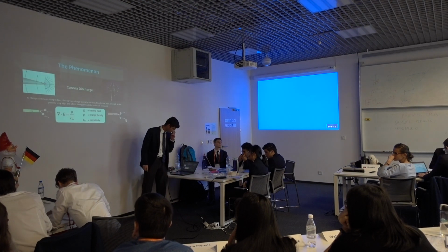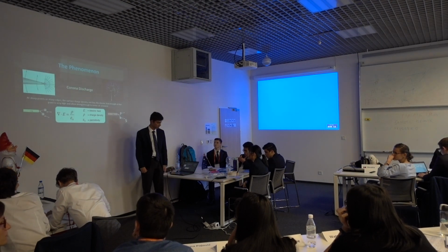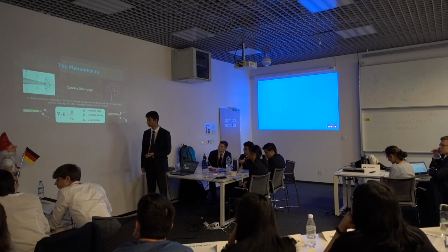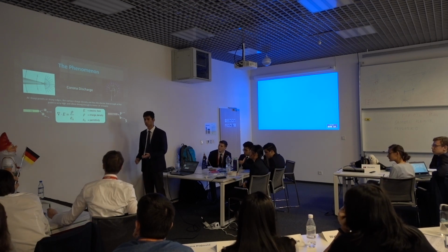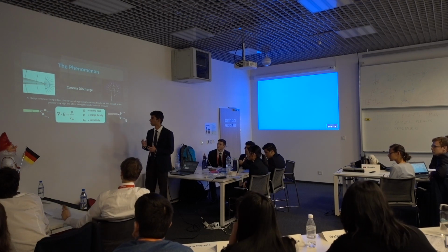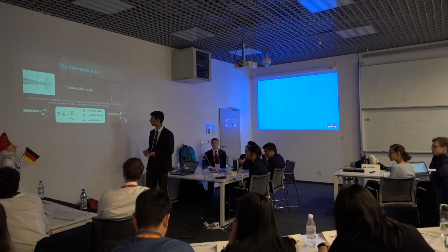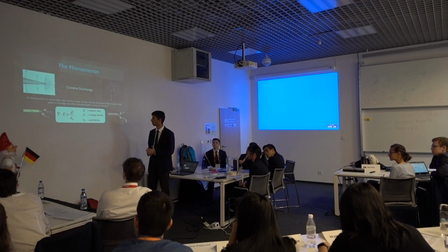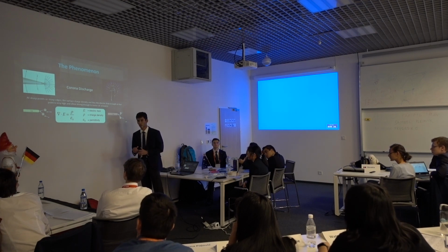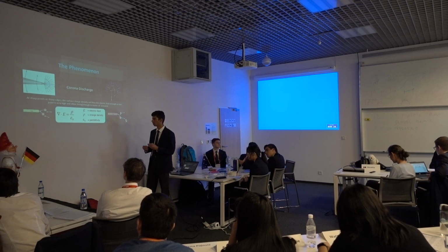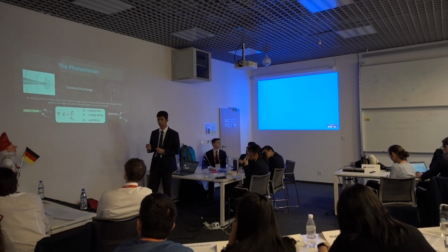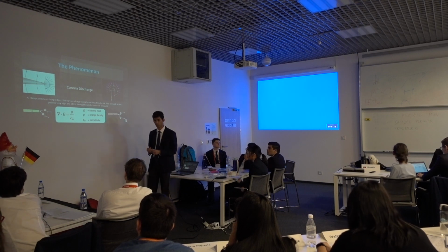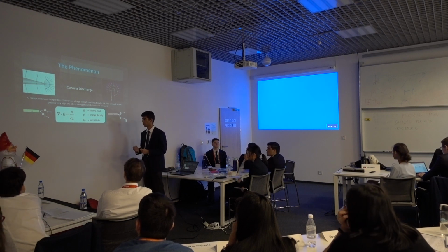The much more interesting phenomenon that is occurring here is corona discharge. At sharp edges or sharp points on a conductive metal, the surface charge density, and thus the electric field strength at that point, is extremely high. And often it is strong enough to ionize the air around it. What that means is the electric field can get strong enough to rip a valence electron out of its orbit of an air atom, and they get separated.